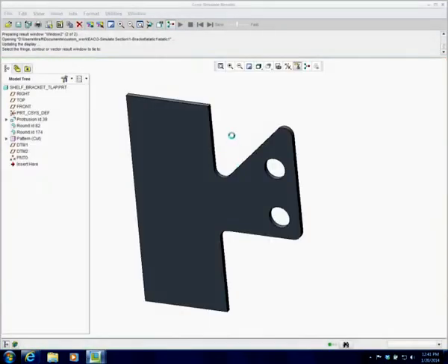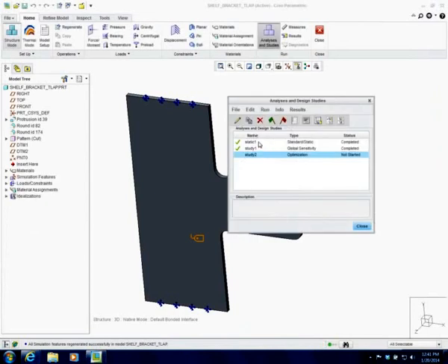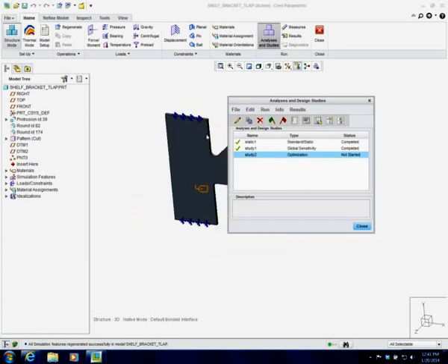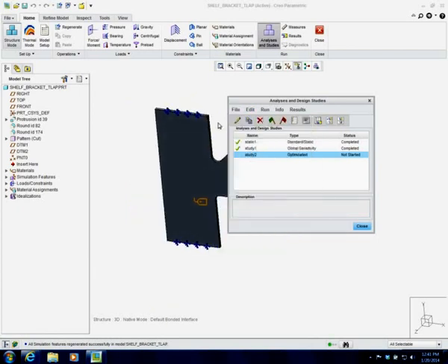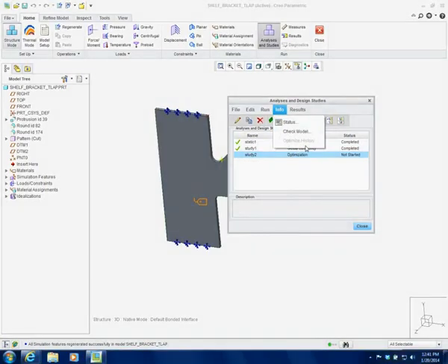Last step is to exit results and click on the optimization study, which is not here. Well, if you had the optimization study here, you would see opt 1, and then you can go info and optimize history, and then you would be able to step through the model and watch it as it changed.